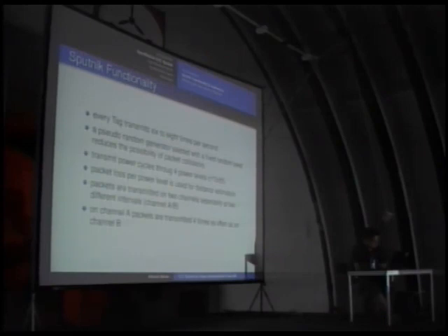Also, we changed the code so that the blinking is not synchronous anymore with the transmitting, because it would cost too much power. If we would blink 8 times per second, it only blinks 1 time per second roughly. So don't be confused. It really sends packets out 10 times a second. Then the pseudo-random generator is again seeded with a random seed. It again cycles through 4 power levels. So you can estimate the distance to a reader by checking at which power levels it is received how often again.